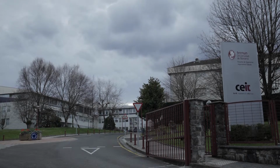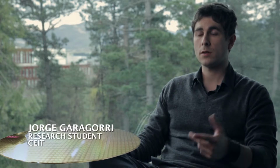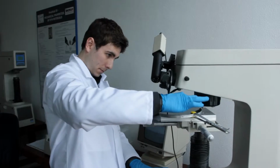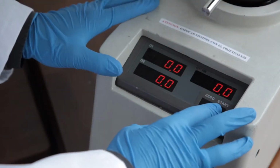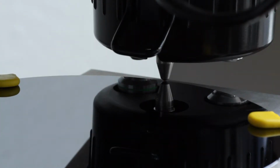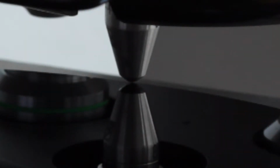The role of CIT in the project is to generate controlled damage within wafers, model the stresses around them, and then try to break them within the rapid thermal annealing furnace. We are creating some samples to deliver to the rest of the partners here. We are using the indentation technique to create some distortion and some fracture on the material. You have a tip. Essentially, you apply a load on the material, so you deform the material, creating an impression and also some cracks and some distortion of the material.